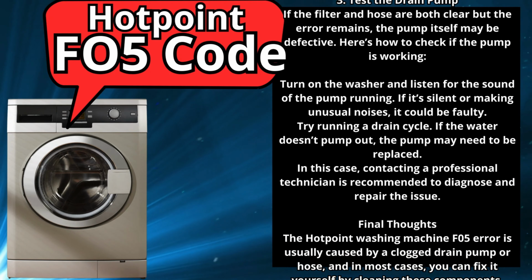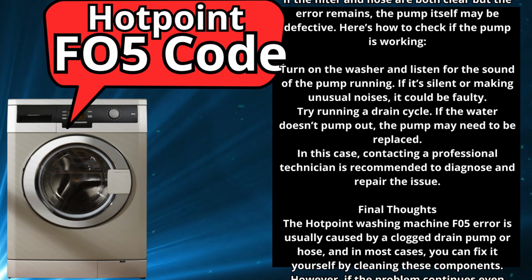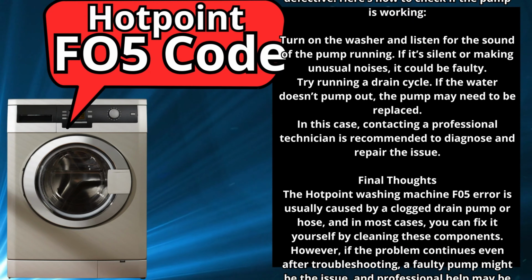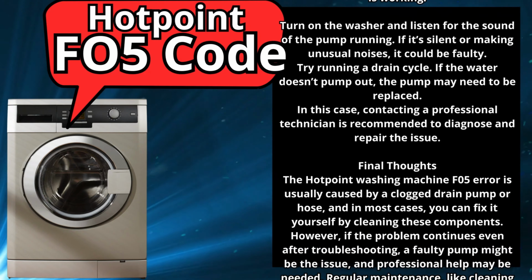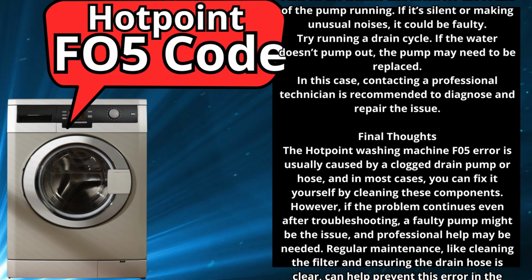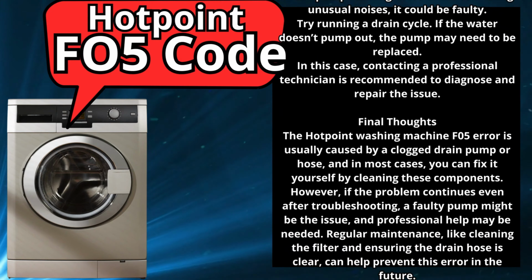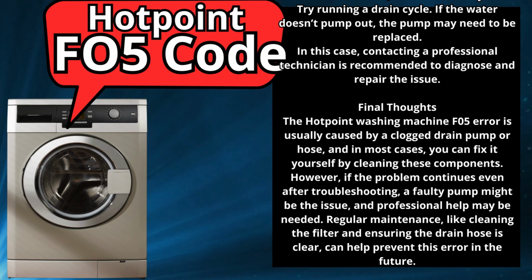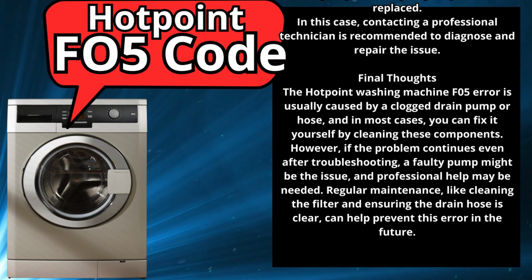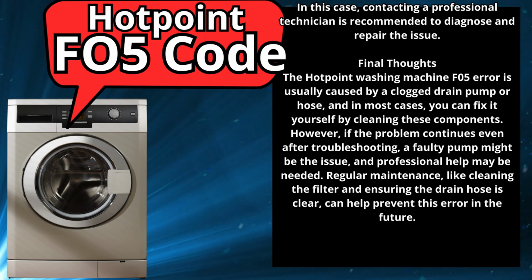Final thoughts. The Hotpoint washing machine F05 error is usually caused by a clogged drain pump or hose, and in most cases, you can fix it yourself by cleaning these components. However, if the problem continues even after troubleshooting, a faulty pump might be the issue and professional help may be needed. Regular maintenance, like cleaning the filter and ensuring the drain hose is clear, can help prevent this error in the future.